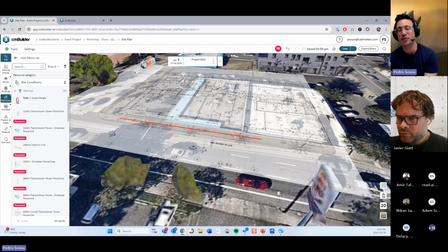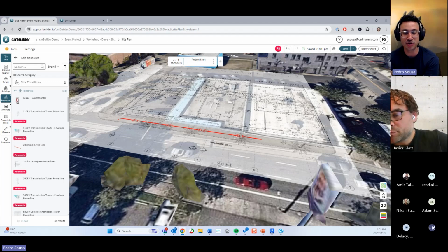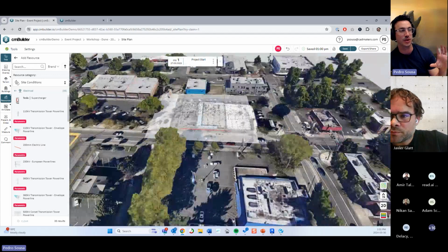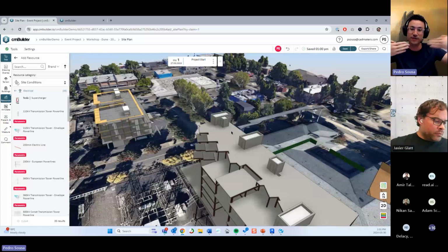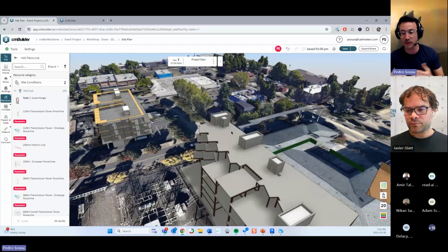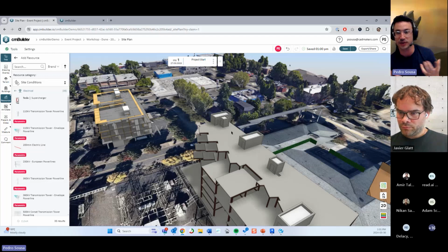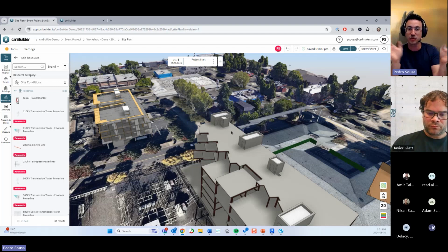Yeah. So for circular elements, using the projection is a little bit harder to convey because the software will understand what the faces are that compose that circle, that rounded geometry. There's nothing we can do in terms of the projection because when it's converted, it converts with those shapes. It's not like in Revit, where you use the actual vector that was created to make that shape and you can edit it. Once the geometry is created, it creates with faces and triangles, so we can only project those faces once they are imported.